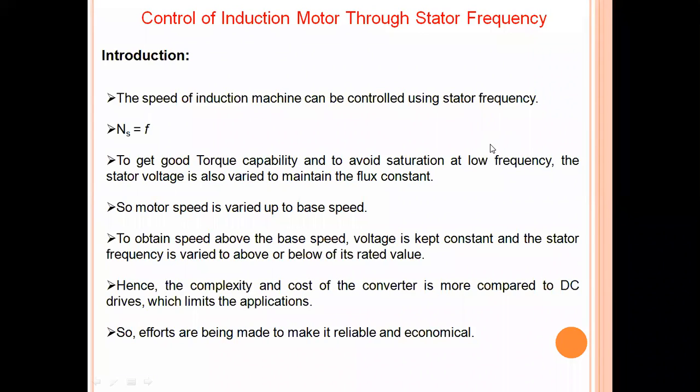Good morning, everyone. In the previous class, we discussed the variable voltage characteristics and the control of induction motor through stator voltage. From today's class onwards, we will see the control of induction motor through the stator frequency. By varying the supply frequency or stator frequency, how the speed or the torque of the induction motor can be controlled, that we will see from today's class onwards.